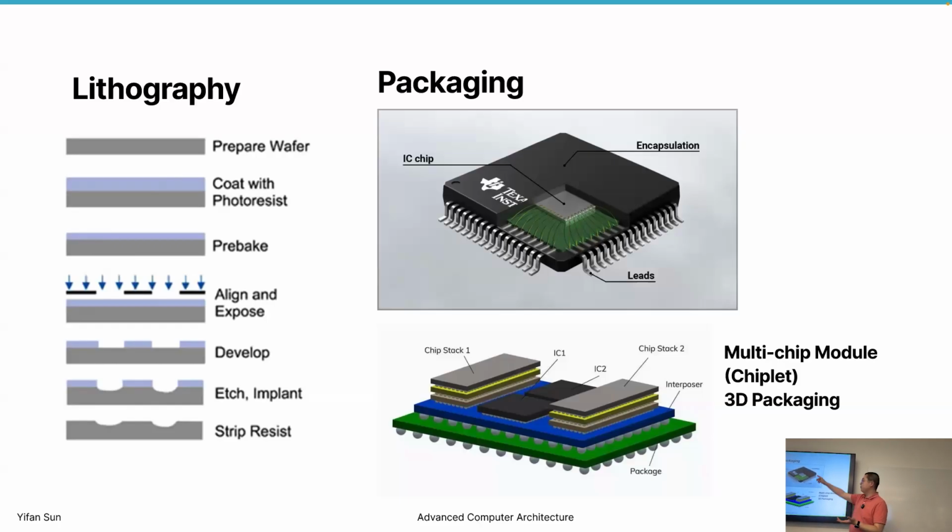They put the chip directly on top of the PCB. Then they drop a piece of plastic or wax or something just to seal it so that it's not interfering with the outside world. So even like this, it provides a basic level of protection for the chip. Even with this, if you touch the chip, the static electricity may damage the chip. But that's something very important.